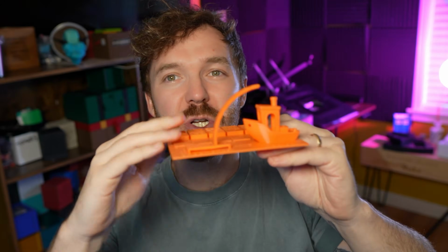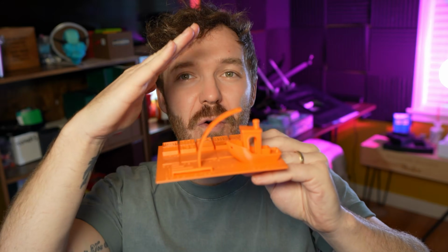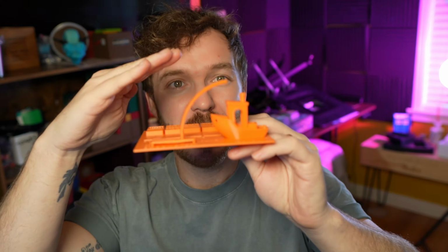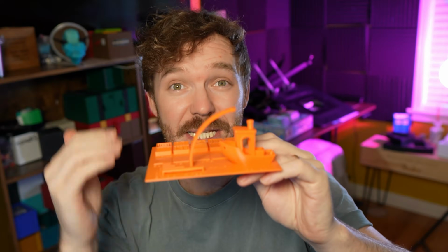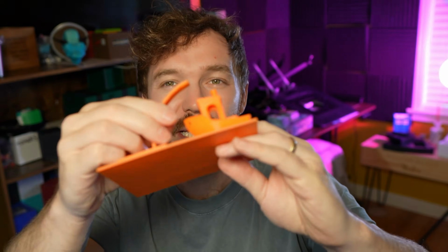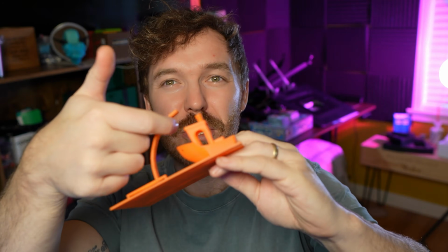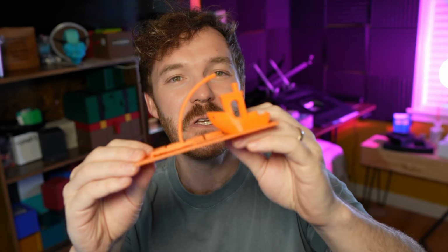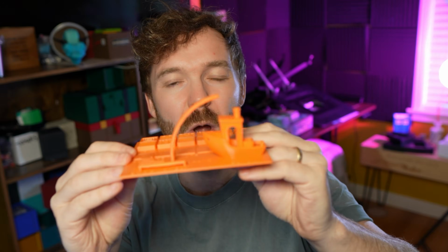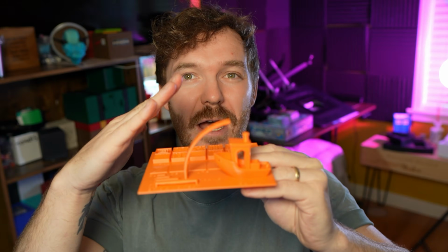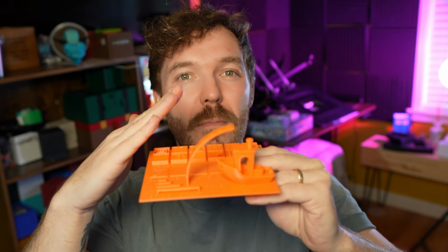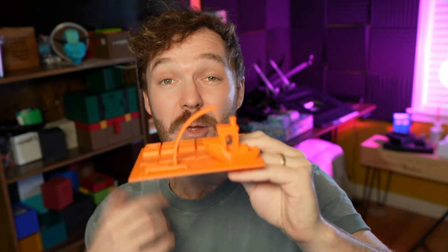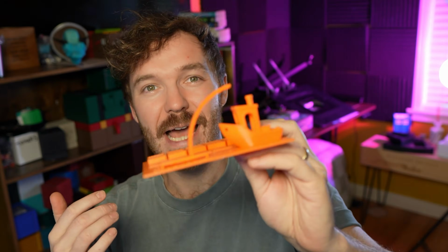Now, what we always want to try and do is not go any further than a 45-degree angle. Now, some printers, like my Bambu Lab printer, can print pretty steep overhangs, which is great, but you can see on this model, it still doesn't look great. And if you're doing really nice commercial projects, you really don't want all those nasty layer lines showing. So always try and print with overhangs no more than 45 degrees. That way you don't have to use any supports and your prints are going to come out looking really nice.